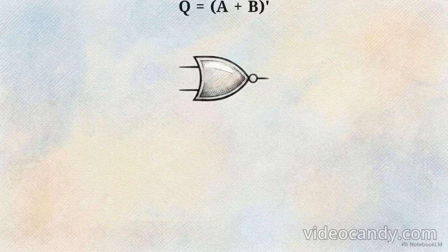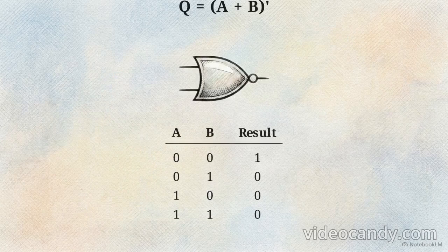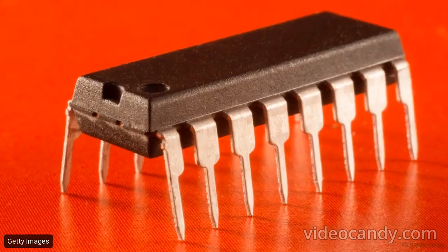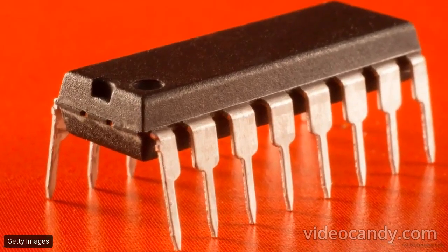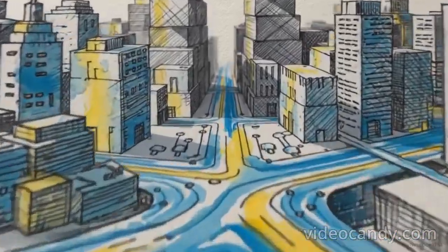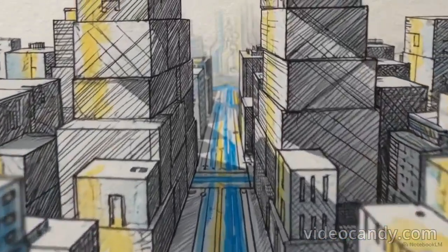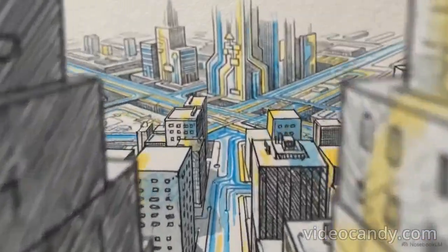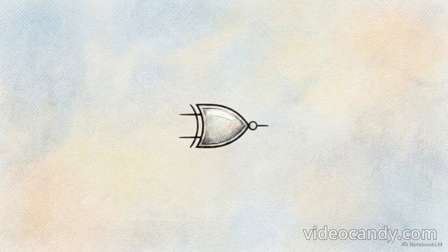The NOR gate acts as the opposite universal building block. It yields a low output the moment any single input registers as high. Running these precise bench tests is how engineers calibrate their components. They have to prove that the physical voltages strictly obey the mathematical truth table before layering these logic gates into a billion transistor architecture. Beyond basic and universal gates, we have highly specialized logic, like the exclusive NOR gate.